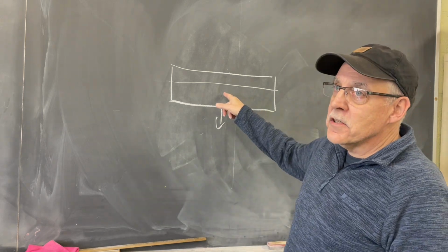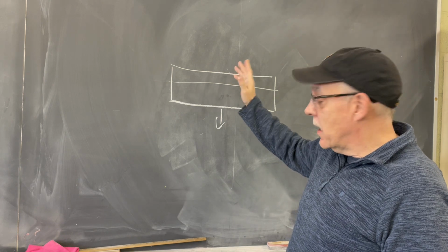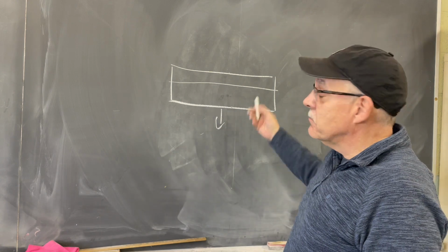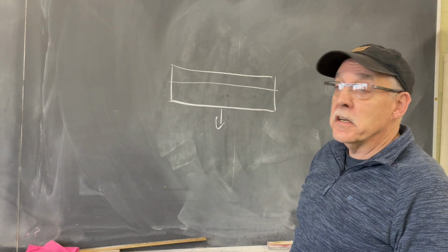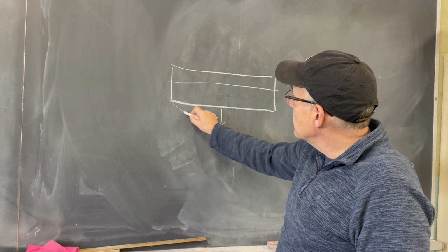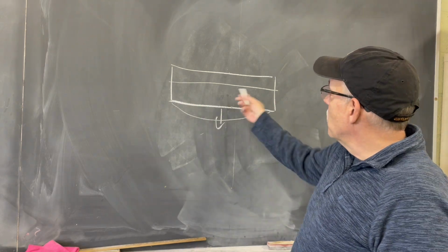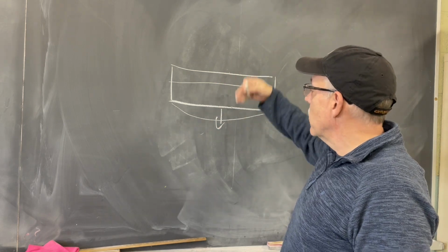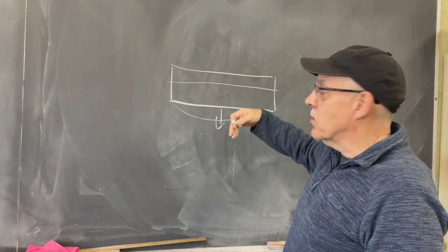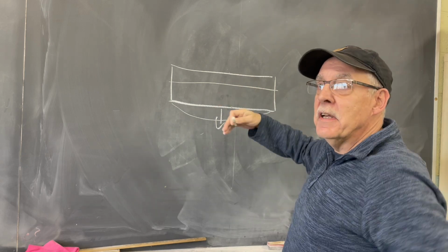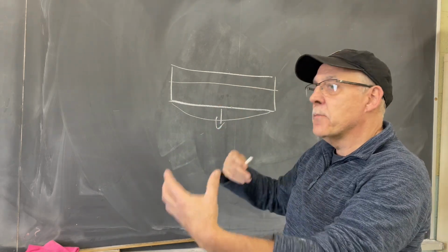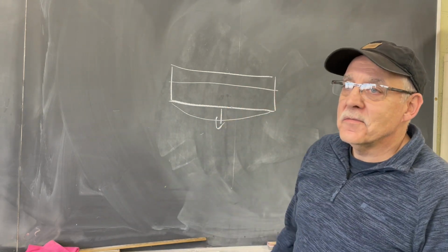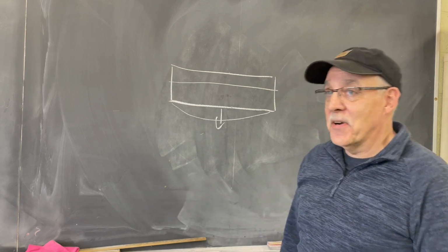The heavier the rotor is, the more imbalance that you will have. Also, when you leave a rotor sit there for days on end, and I've dealt with rotors that weigh 60, 100 tons, they sag, so they bend a little bit. So already you have imbalance in that, and you have to run it for a while to take the imbalance out of it. When you start that up, there's going to be more vibration. Then as it warms up and everything gets up to temperature, the sag comes out of it, and the vibration will go down a little bit. Never a situation where there's never any vibration.